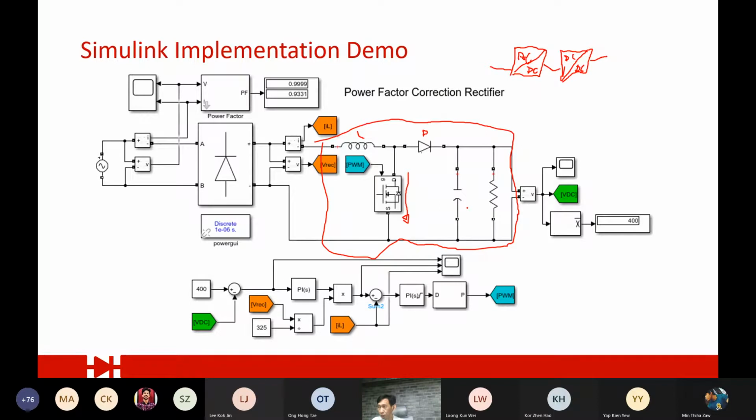Because we don't have the control, that's why we have the non-linear output. We cannot control it, but with this one, the PWM is set by the feedback control here, so we can control how the capacitor charges and discharges. So we can actually make the input current a sine wave and do the power factor correction. Just simply combine these two known things, plus the double loop control. So this is how people work things out innovatively.